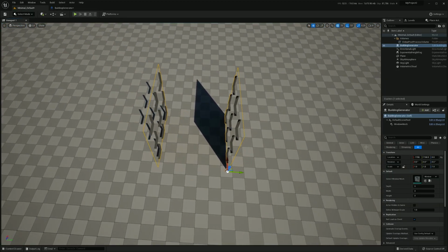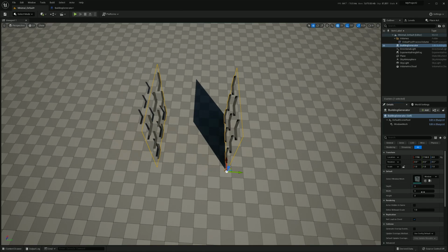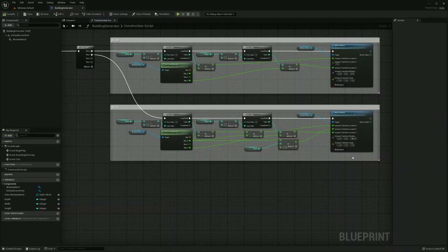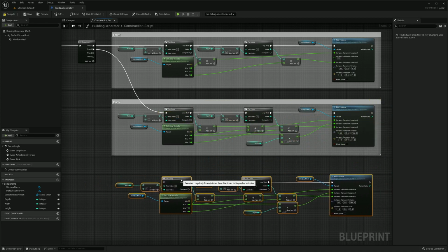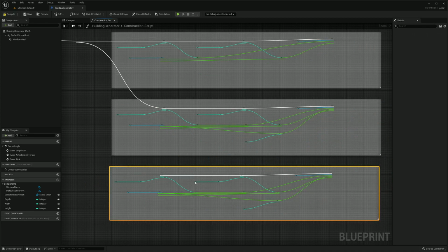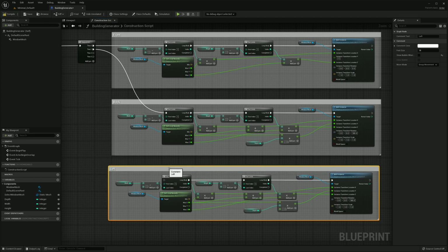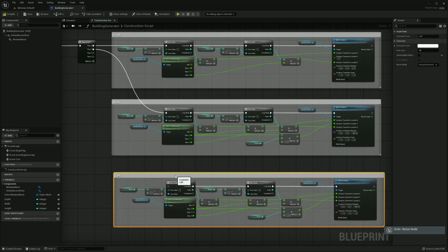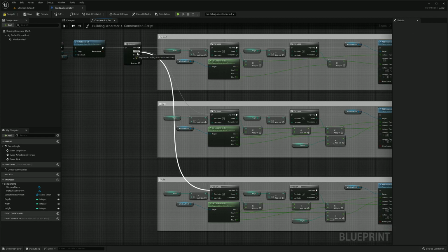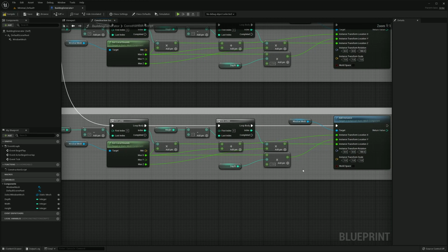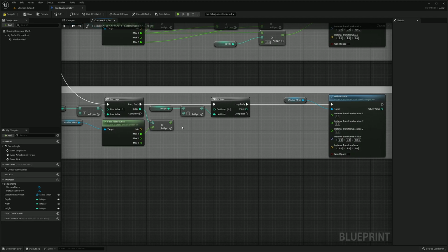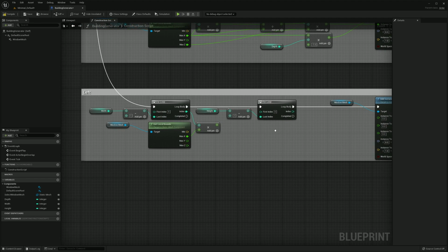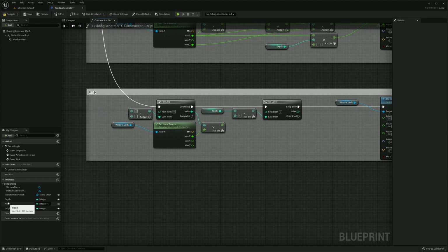And all that works great. So now we just need 2 more walls and a roof for it. For the left wall, we can duplicate one of the previous walls and replace some values again. First we need to change the width to use depth instead.